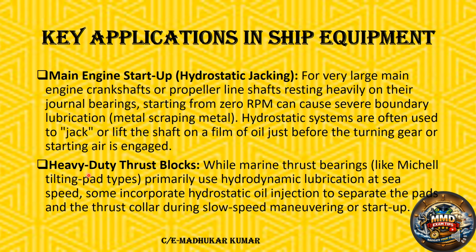Thrust pads, heavy duty thrust pads. A marine thrust bearing is typically a tilting pad bearing type. The thrust bearing primarily uses hydrodynamic lubrication at sea because the speed is there. Some incorporate hydrostatic oil injection to separate the pads and the thrust collar during slow speed maneuvering or at startup time. At startup, or at slow speed, like dead slow ahead, dead slow astern, and slow ahead and all, these things are there. Anyway, thrust block lubrication and all is a separate topic, so we will discuss it afterwards.